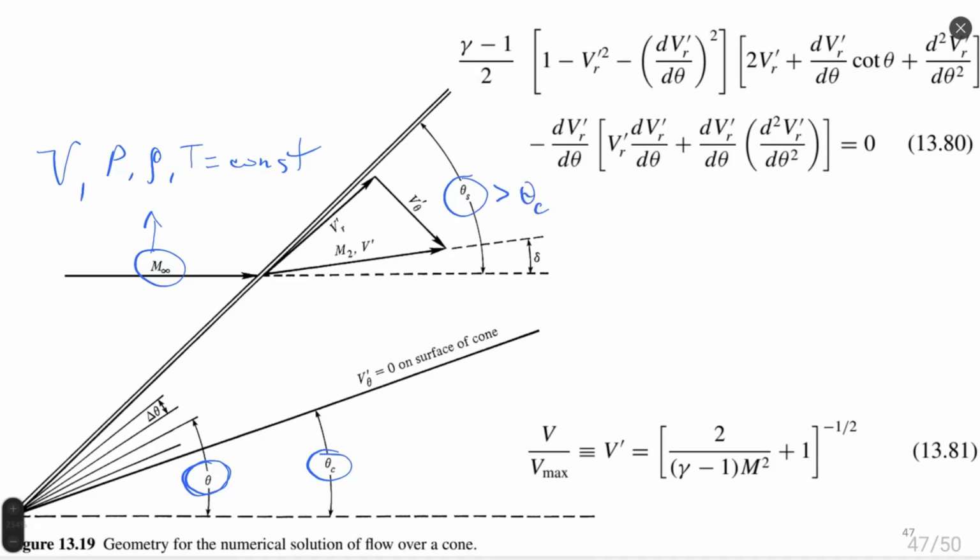As we can see from the theory of hypersonic flow, and we will see very soon, there is a relation between theta s and theta c for hypersonic flow. So we can use some similar relation for supersonic flow, and we can guess what would be a good value for the initial parameter of theta s. On this shock wave, we assume the boundary condition velocity calculated by oblique shock wave theory.